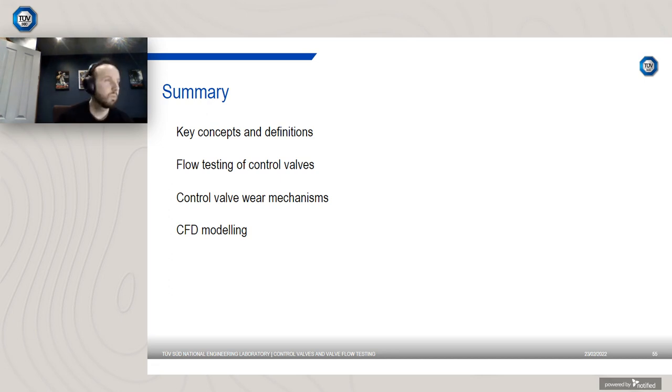So that's basically the end of the webinar. I'll just kind of briefly go through what we've covered. Started off talking about control valves. What is a control valve, some of the different types and styles, and what are some of the selection criteria that you should consider when choosing a control valve for use. Went over some key technical concepts and definitions like flow coefficients, pressure recovery factors, cavitation, flashing, and choked flow.